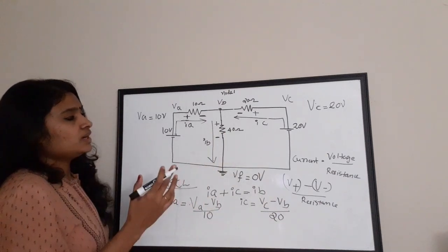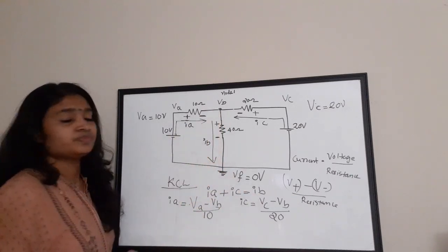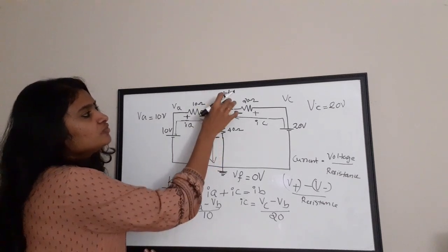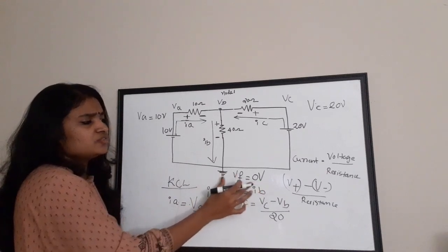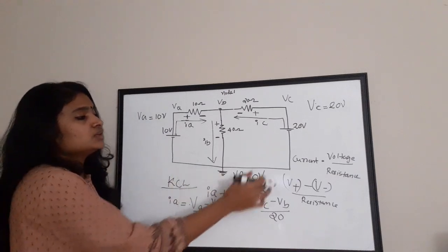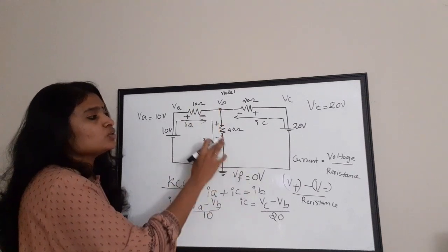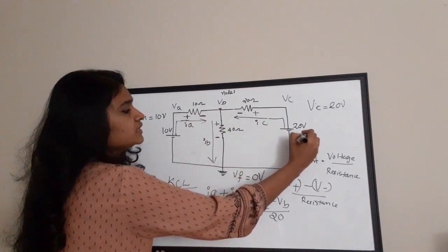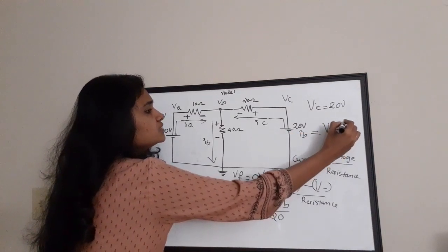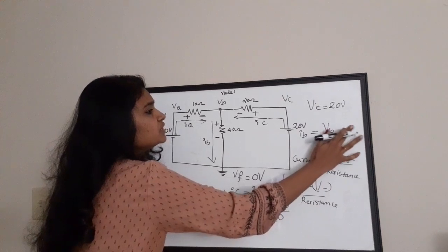Okay. Now we have to write the equation for the last current, which is IB, the current through this branch. So the current equation is V plus minus V minus, or VB minus V minus. Here the V minus, or the lower potential, is 0 because the current is going to the ground. So the V minus is taken as 0. So VB minus 0 by 40. I'll write the equation here. That is, the current IB is equal to (VB minus 0) by 40, or you can write it as VB by 40.